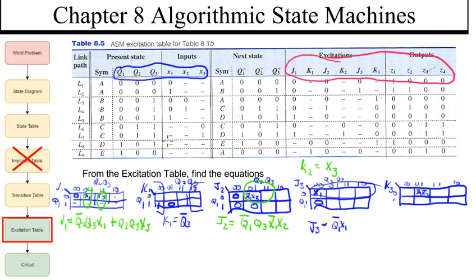Zeros are going to be for the 0, 1, 1. The 0, 1, 1 state is going to be a 0. So those two zeros translate to 1, 0 there because we're combining these two rows. And then 1, 0, 1 is going to be a 1. And I don't care about this one. So that's it. Okay, what can we do? We can make a big implicant right here.